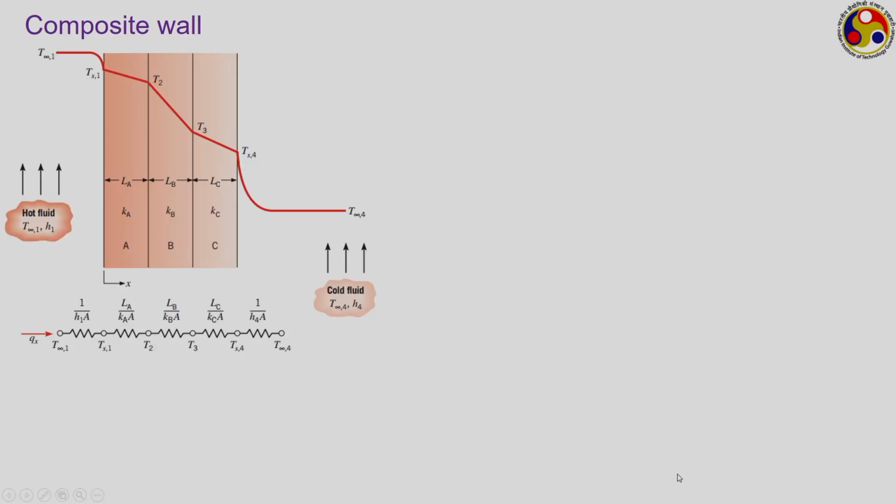Just look at this, something known as a composite wall. Here instead of one, there are 3 layers of solids inside the wall. Then we can think each of them are having different thermal conductivities. So, we can think about there are 3 different conduction resistances acting in series with each other. Look at the first part, the block A of the solid. The temperature is Ts1 at one side and T2 on the other side. Then if we consider that Q̇x is the amount of heat transmission that is taking place by conduction, it is 1D and steady state. Please remember that whatever we are discussing, that is applicable only for one dimensional steady state heat conduction.